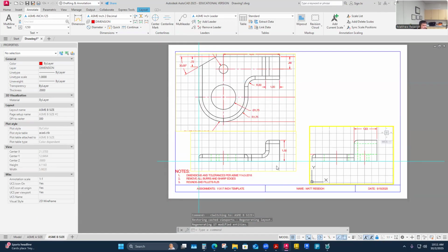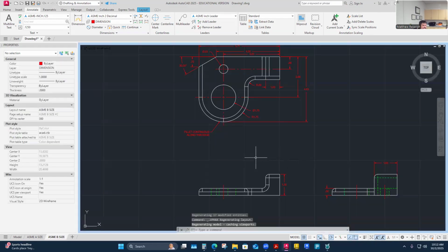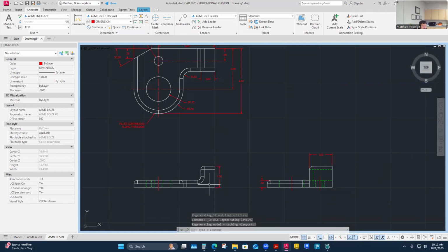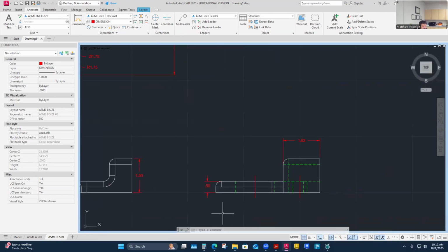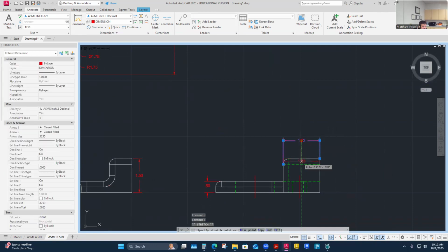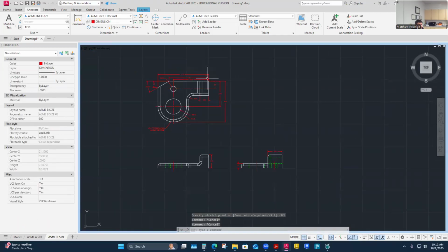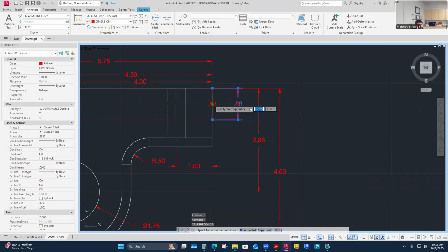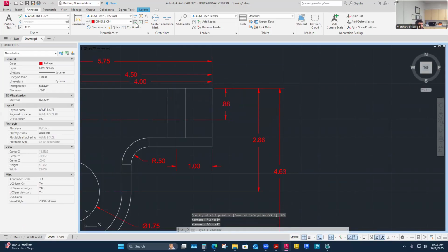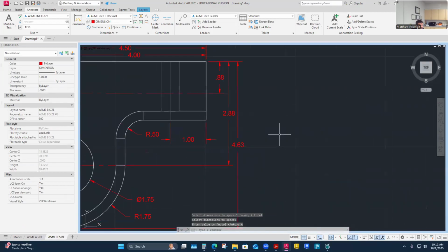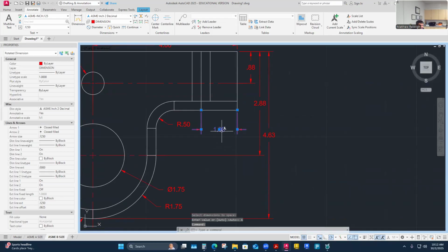I think I'm still going to be able to make this work. I'm just going to have to resize my top viewport, but I'm not going to worry about that until I get the dimensions spaced how they're going to be. So I've got to fix my spacing still. I actually just did my front view one. It's the only dimension I have there. These are 0.375 away from the object, the intermediate dimension. I'm going to space these other ones out, the auto space. This one's an intermediate dimension as well.